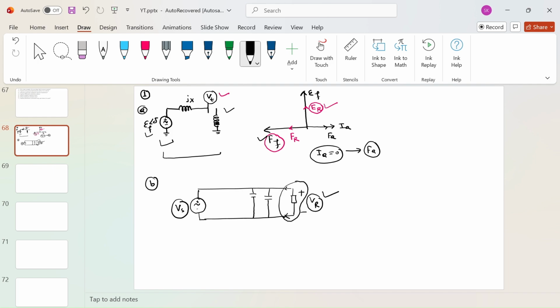So how do we deal with this kind of thing? We can have a shunt reactor at the receiving end to limit the terminal voltage, or the receiving end voltage. This is how we have to deal with the over voltage because of the Ferranti effect.